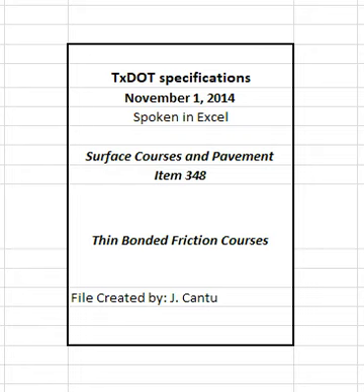Suspend operations and take immediate corrective action to eliminate severe thermal segregation unless otherwise directed. Resume operations when the engineer determines that subsequent production will meet the requirements of this section.